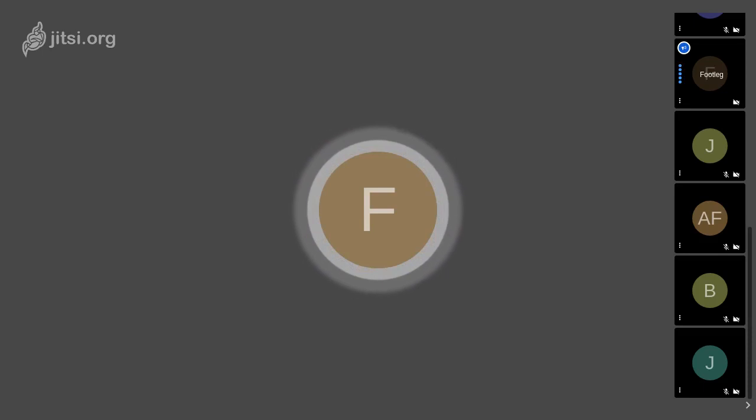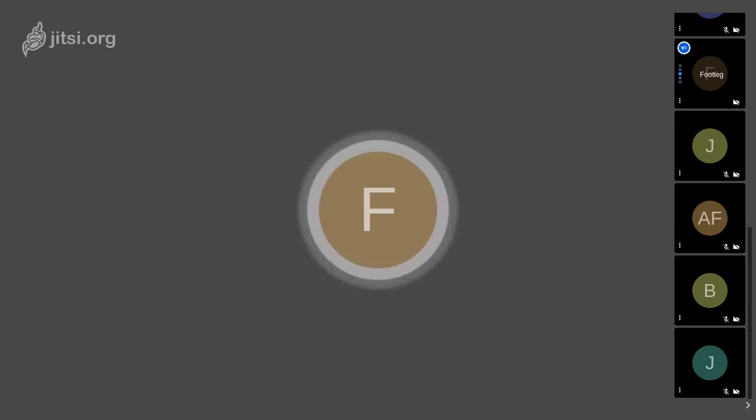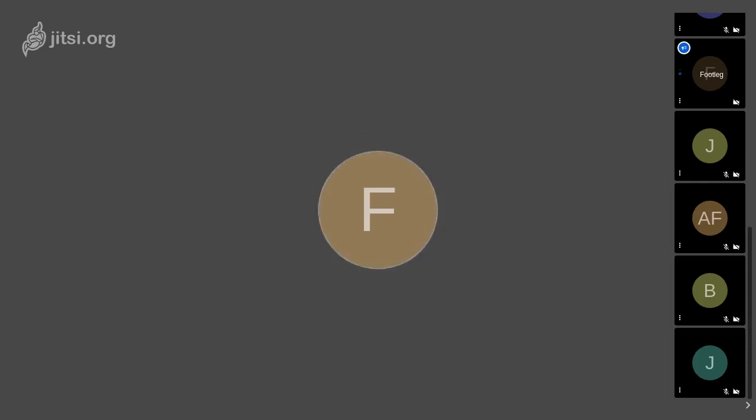But I did find that for single layer stuff, so just doing silk artwork, I could just export from Inkscape as DXF, and you can import DXF directly into the footprint editor in KiCad. And that enabled me to get some quite complex artwork onto my silk layer.